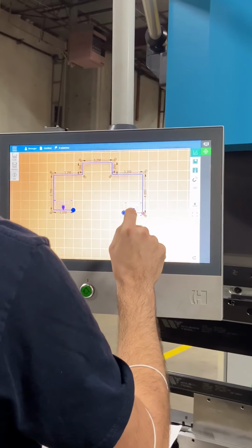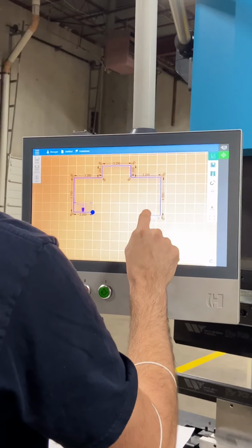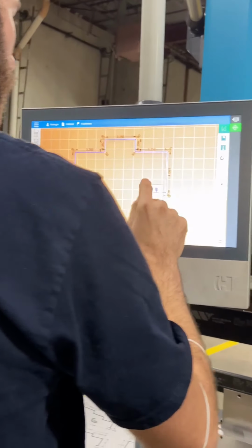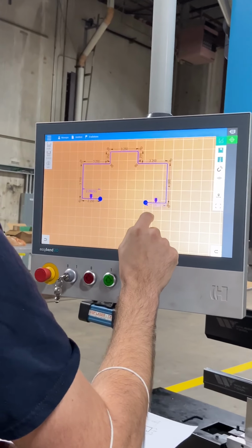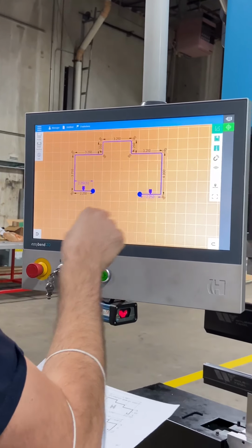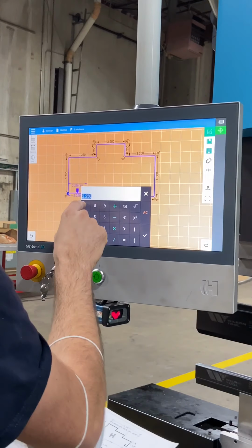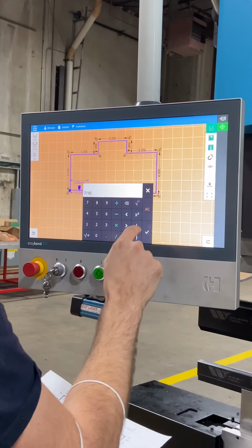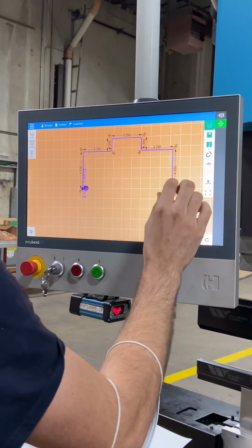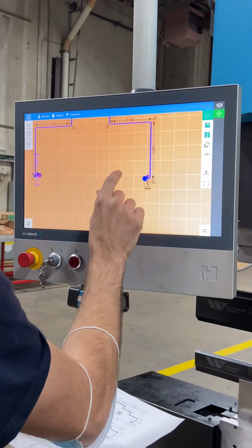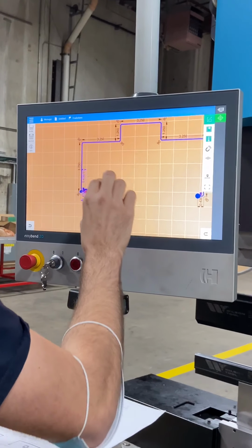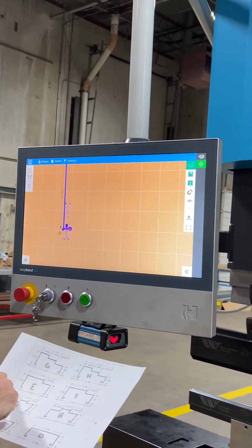Because you're changing it by typing it, it gives you the variable. So I'm gonna go back. I'm gonna go boom, so 1. So now you can see it automatically change. So if I change this variable to 7/16, boom. So now it changes both of them at the same time, right? Yeah, that's because I defined the variable, and that applies to the outside.